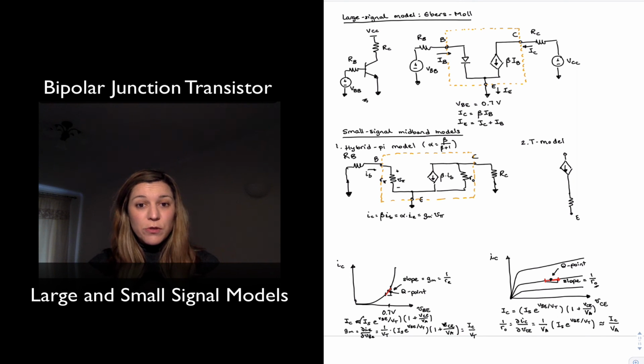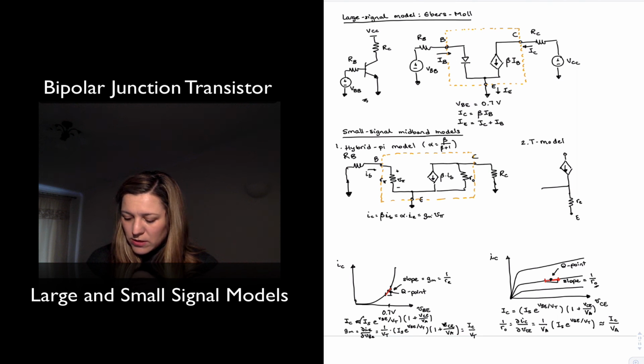You're still representing your base to emitter connection as a resistor because of that forward junction that's going to behave as a diode, and for small AC signals as a resistor. Now you're representing this as little re because this is just the resistance that is truly connected to the emitter, not looking from the base. The base in this case is connected here.